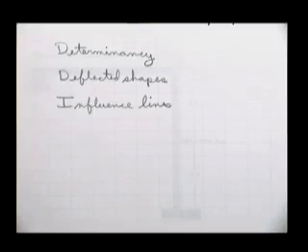All right, we have been discussing determinacy and the dark side, indeterminacy. If a structure is statically determinate, you will be able to solve for all the forces, shears, moments inside of the structure using statics alone.